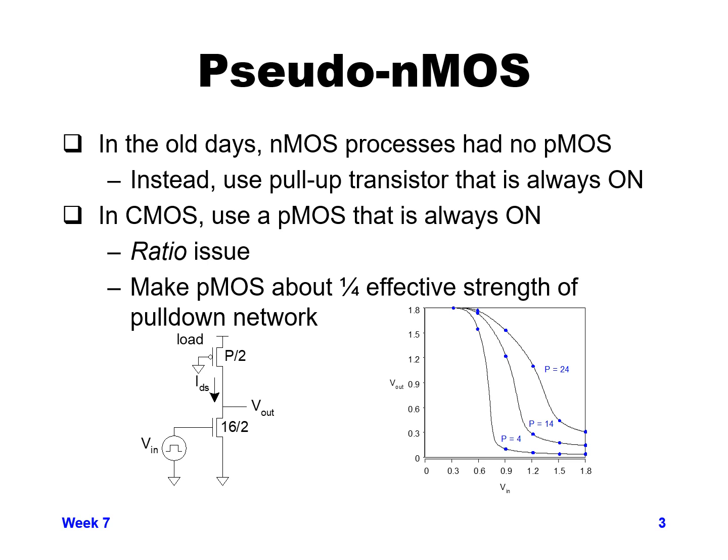And so if any transistor in the pull-down stack turned on, it would override and be able to pull the output to low. But again, if you use an NMOS to try and pull up, it doesn't get all the way to the rail. So in CMOS, we have PMOS devices, and if we're trying to use pseudo-NMOS logic, we'll use a PMOS device that's always on. So you can see below